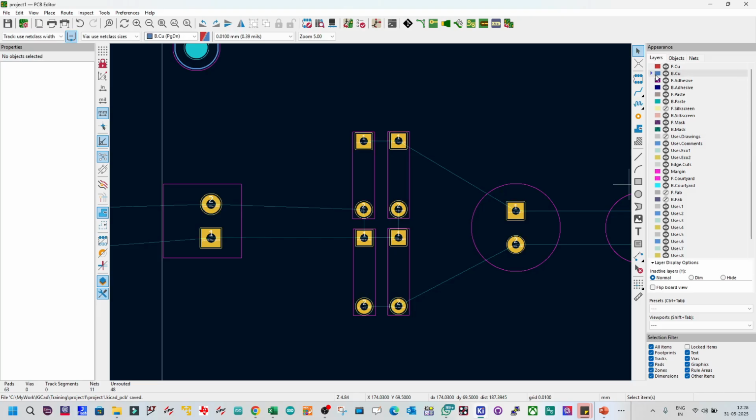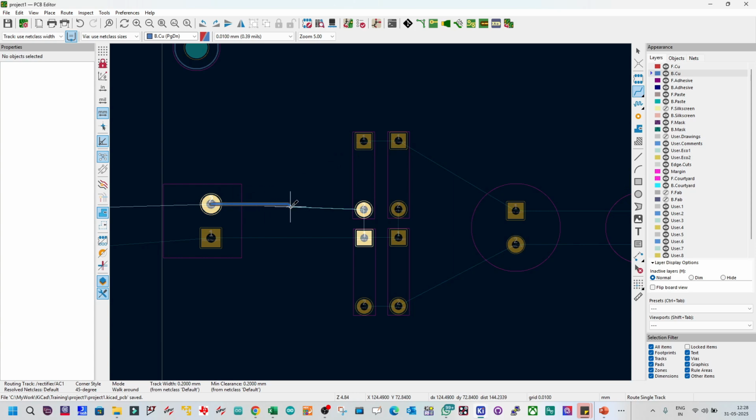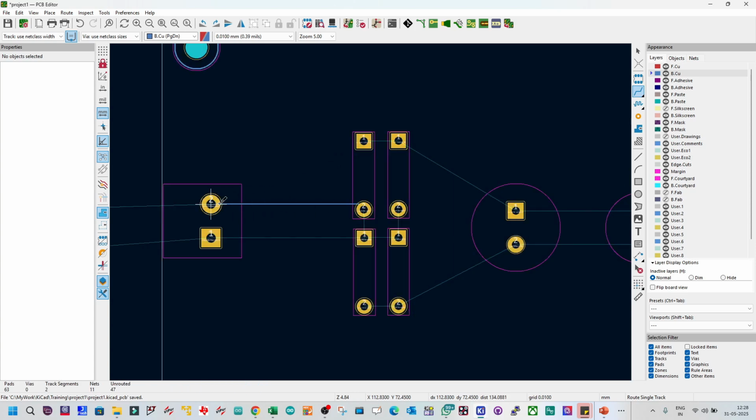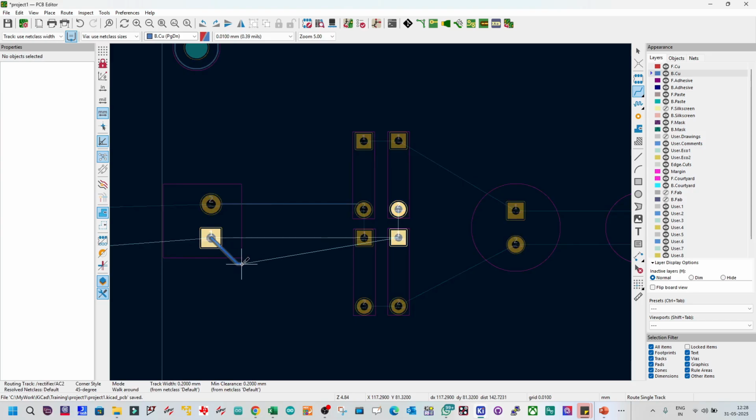Bottom. So I will select the bottom, select the route tracks. I will select one track and route it. Start from here, click and drag to the right side and drop it here. Once you click, it is selected. You just drag your mouse. Now you see, if you move here and there, the segment is formed accordingly. Where you feel the way you want to route is being advised by this tool, there you just click left.